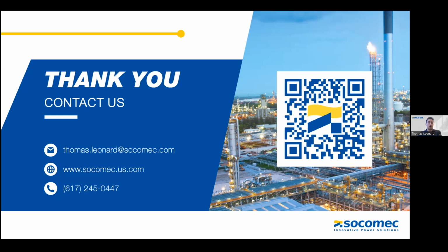Okay, it's generating harmonics at the load level, but what impact does it have on the rest of the distribution? Does it have an impact upstream, and does it have impacts elsewhere on other loads? That's what I was talking about on the propagation of harmonics pollution. So it's really to be able to investigate the origin, the location, and the impact of harmonics pollution. Yes, installing multiple power quality meters closer to the load is recommended.